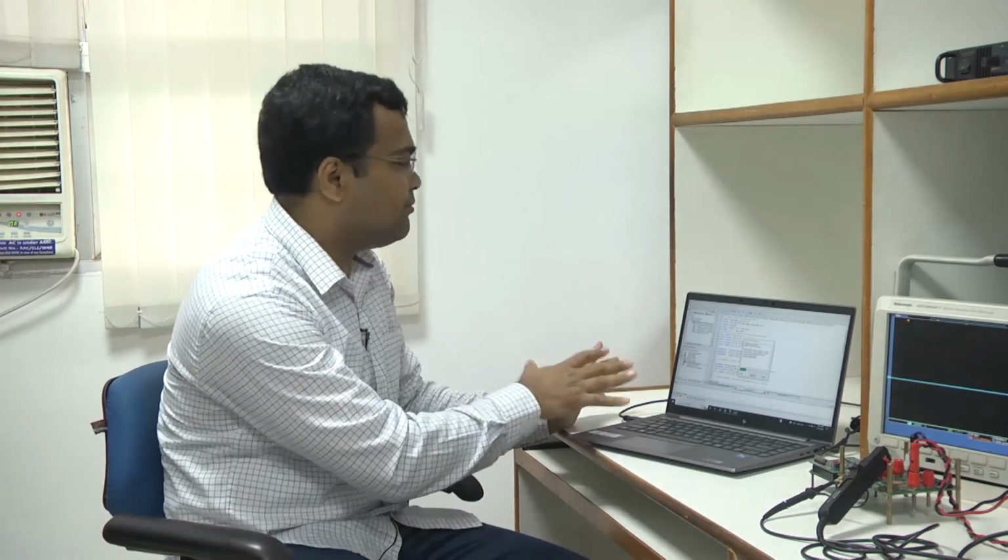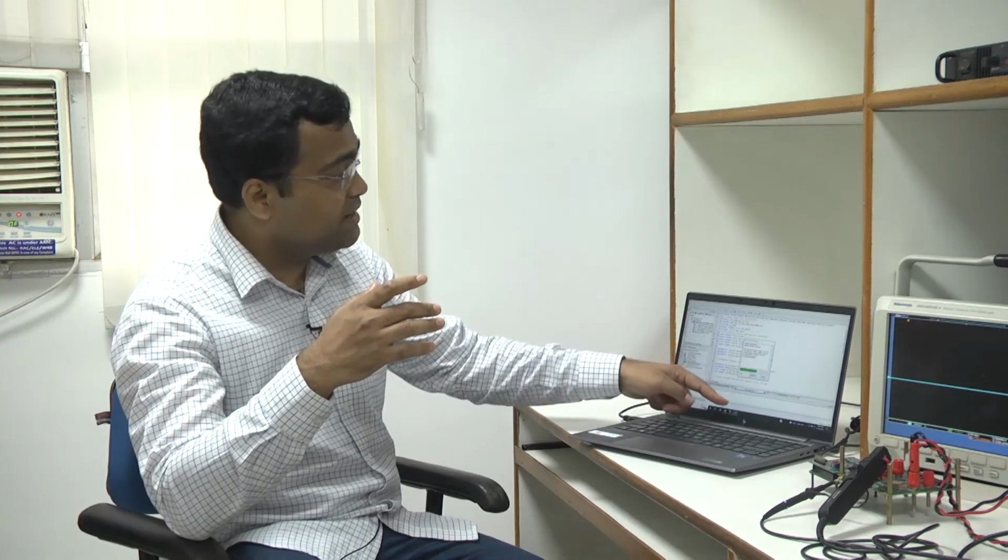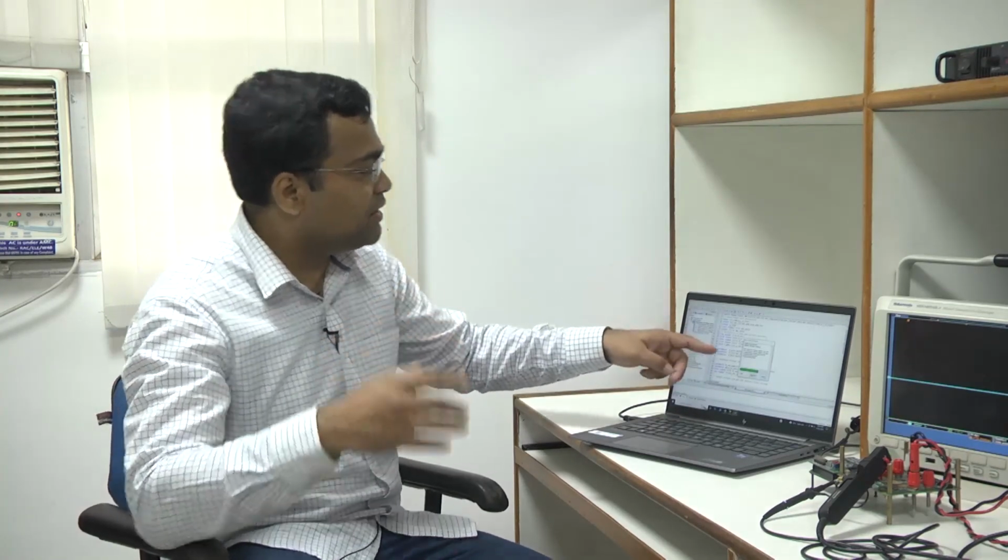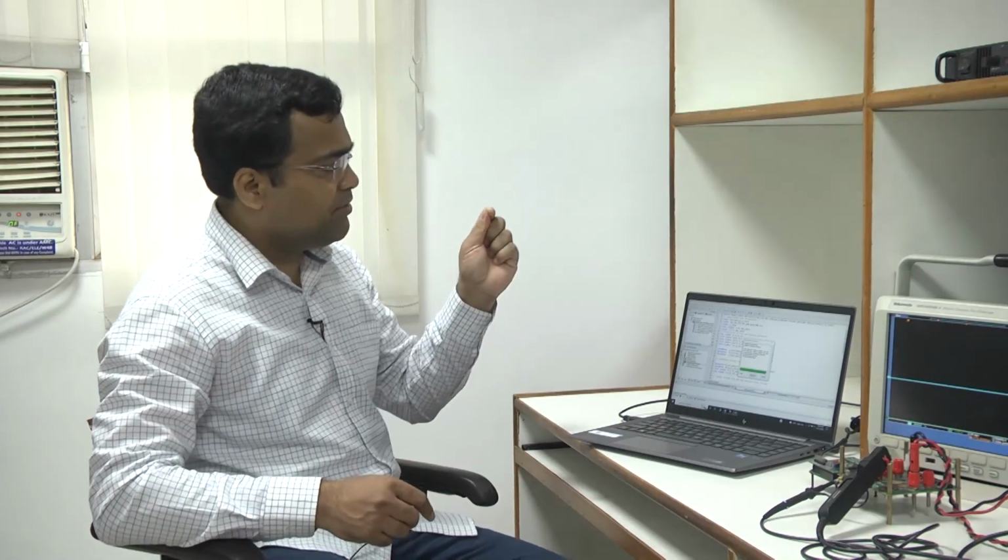This is the step where our Verilog files are synthesized, it generates the implementation detail for the FPGA prototyping, and it also generates the .bin file. Now, this bin file we are using with another interface, and we have demonstrated the FPGA configuration for this particular FPGA, and now this program is being dumped into the FPGA. It will take maybe less than a minute to complete.